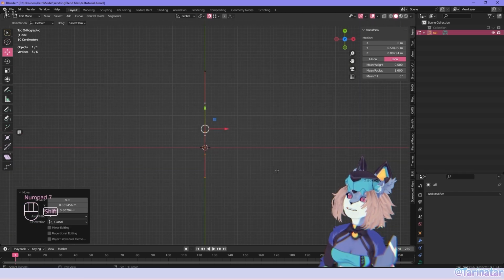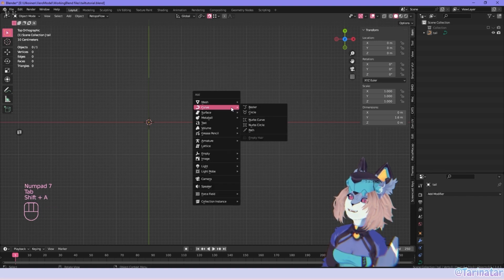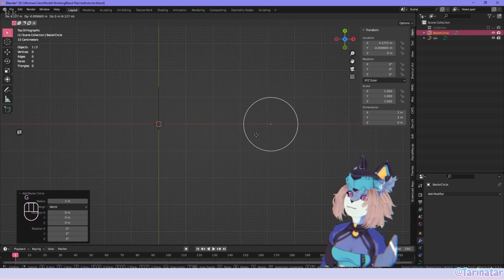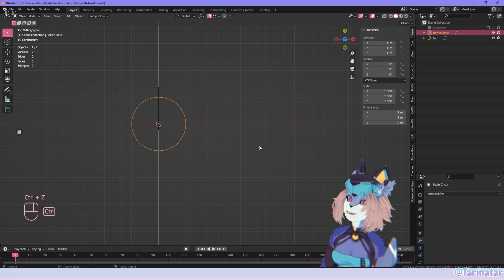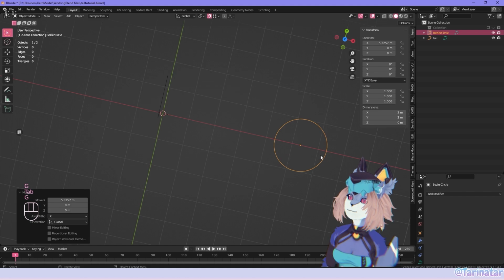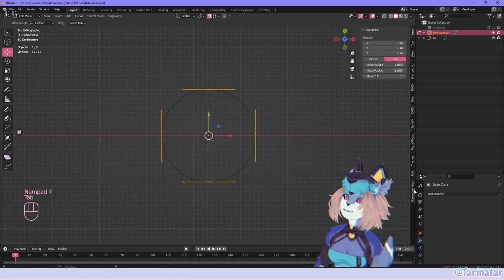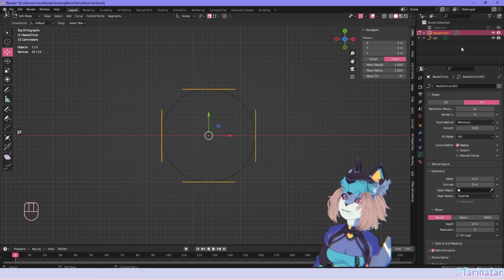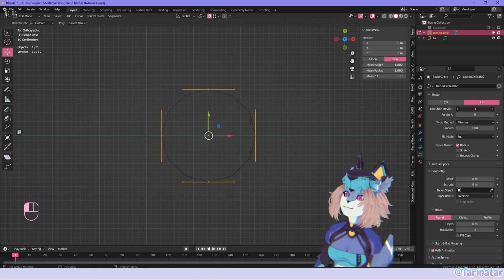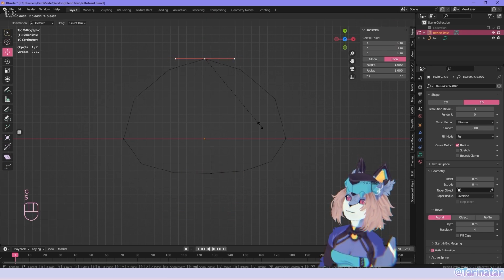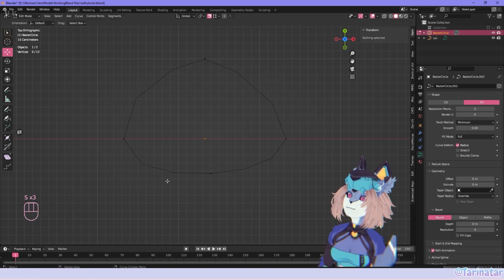And let's now give it some shape. We do that with another curve, the circle curve. And we can move this to a side as long as the origin moves with it, so don't move it in edit mode. Move it with object mode. There we go. And let's tweak it a bit. We have a curve object data properties panel here where we can lower the amount of vertices on it and make it more tail shaped.